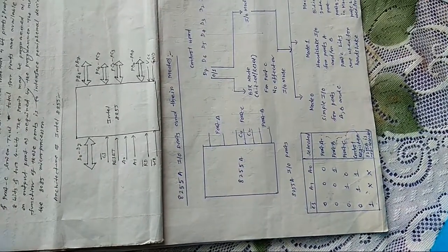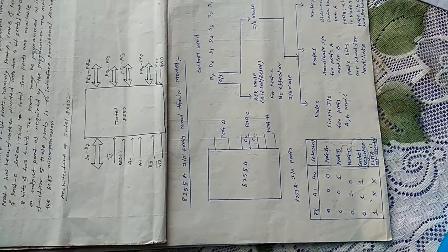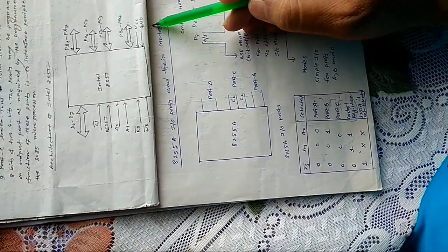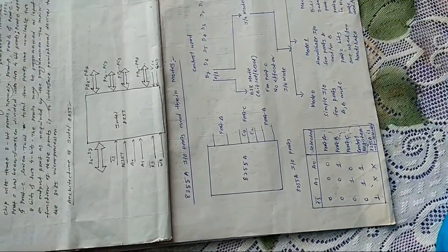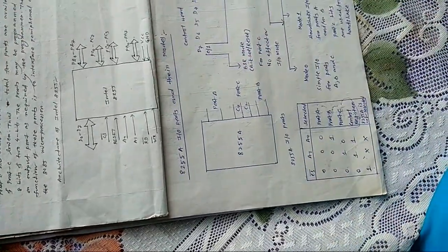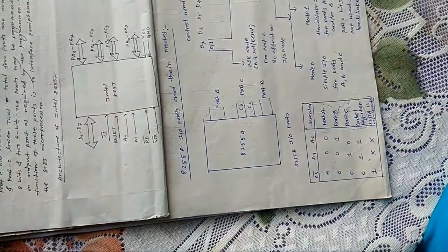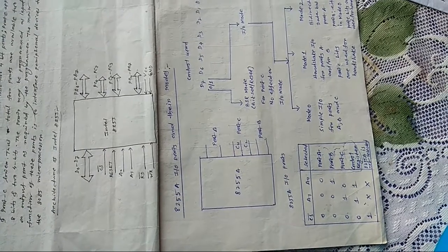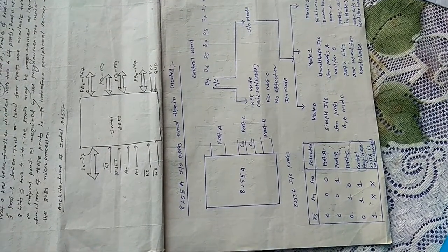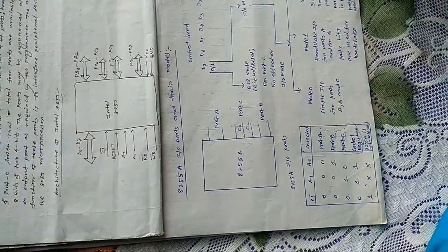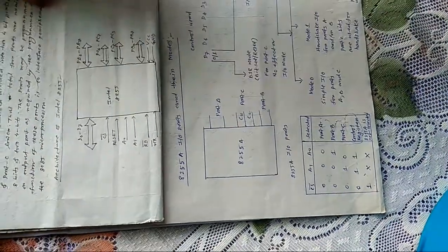Okay, and 8255 requires the plus 5 volt VCC and ground, and another control signal which is reset. So when reset is 1, that means the control register value will be 00, reset. Okay, now I think that all of you understood properly this 40 pin.